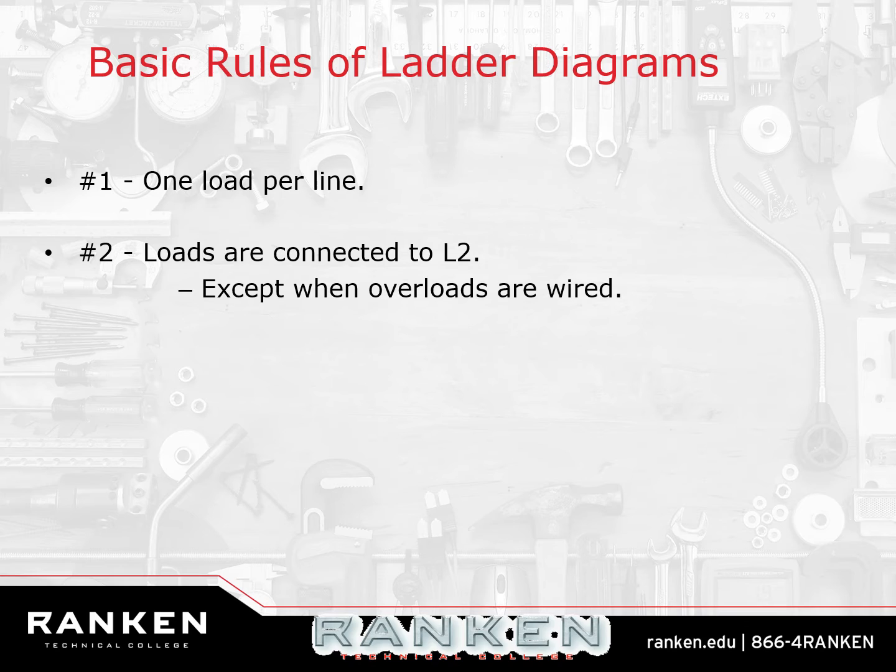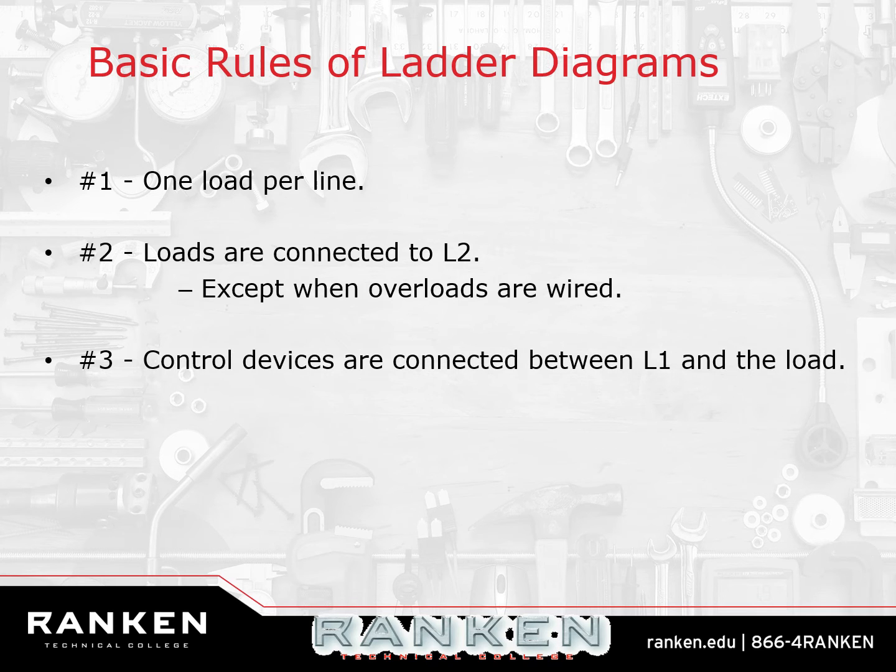Rule number 3 is, anybody know? All control devices are connected between L1 and the load. Control devices meaning things that will control the current: switches, contacts, buttons. All of that stuff needs to be connected between L1 and the load. Not between L2 and the load.